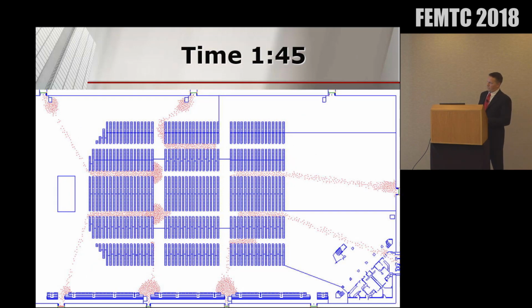And as time progresses in this model, we see some inappropriate things. Perhaps we wouldn't expect queuing here when these occupants wouldn't need to wait in line if that barrier were not there. But if we remove that barrier earlier in the analysis, these occupants would follow the shortest path to an exit, and this queue would be very large.